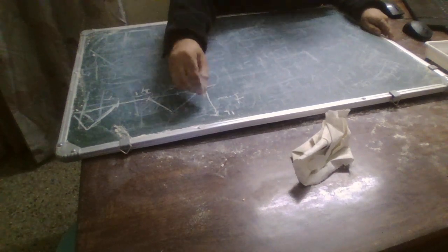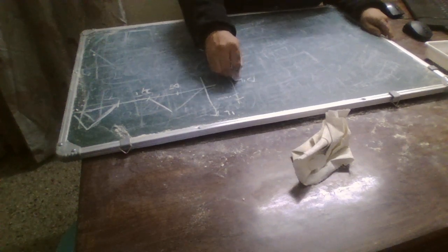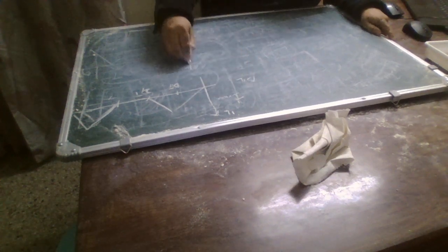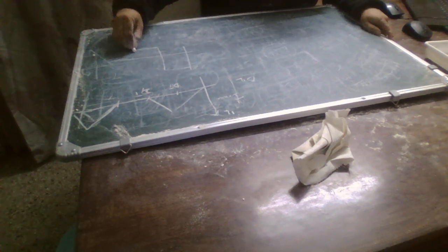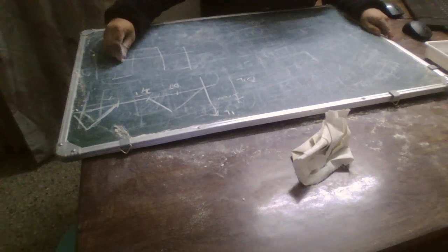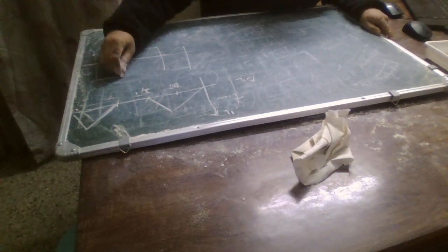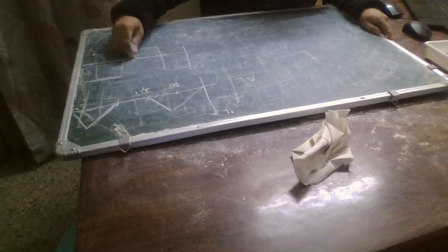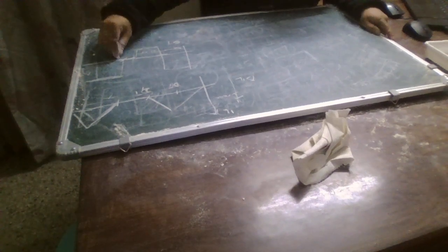Again, the difference of this to this is delta IL. The inductor voltage was like this in the continuous mode, but here it would be this. This was a similar graph. If you see the buck converter also, I have done the same thing. This was DT, this would be D1T, and this is T.